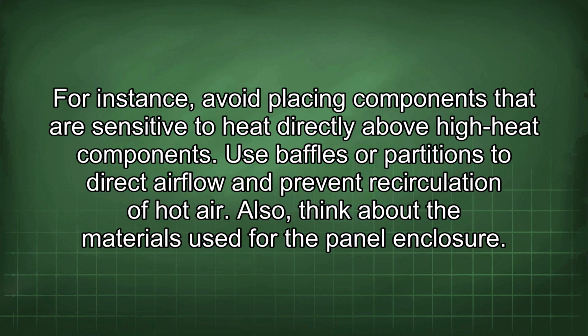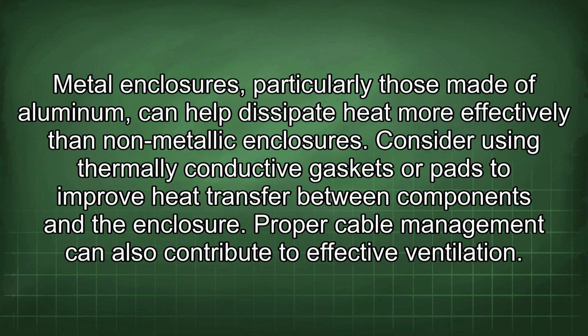Also, think about the materials used for the panel enclosure. Metal enclosures, particularly those made of aluminum, can help dissipate heat more effectively than non-metallic enclosures. Consider using thermally conductive gaskets or pads to improve heat transfer between components and the enclosure.